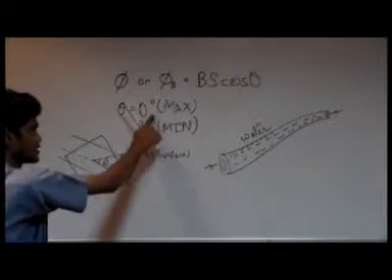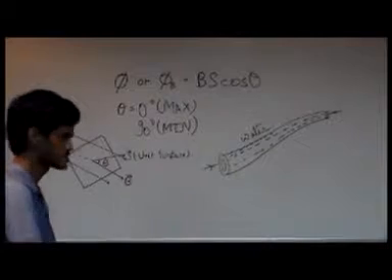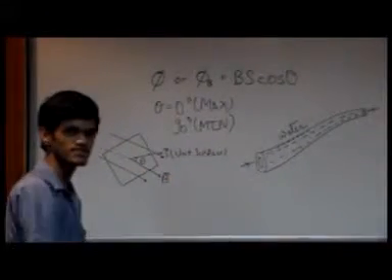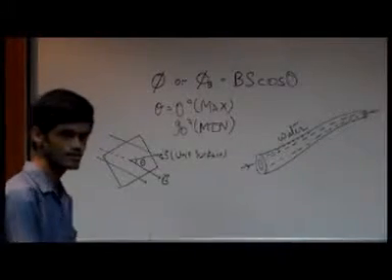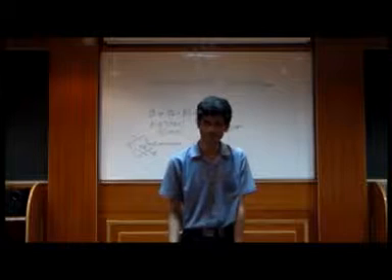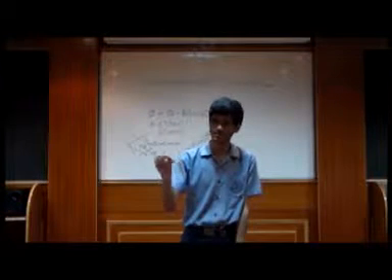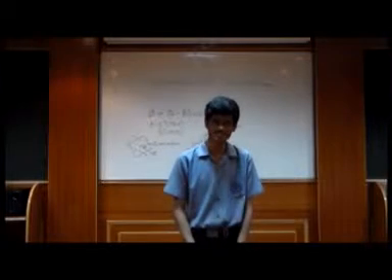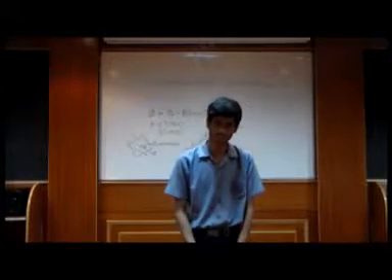If it is 0 degrees, it is maximum as we have just seen, and if it is 90 degrees, there is minimum chance of these fields to pass through, and thus minimum magnetic flux. The SI unit of magnetic flux is Weber, represented by the symbol Wb, and its CGS unit is Maxwell, named after the great scientist James Maxwell.